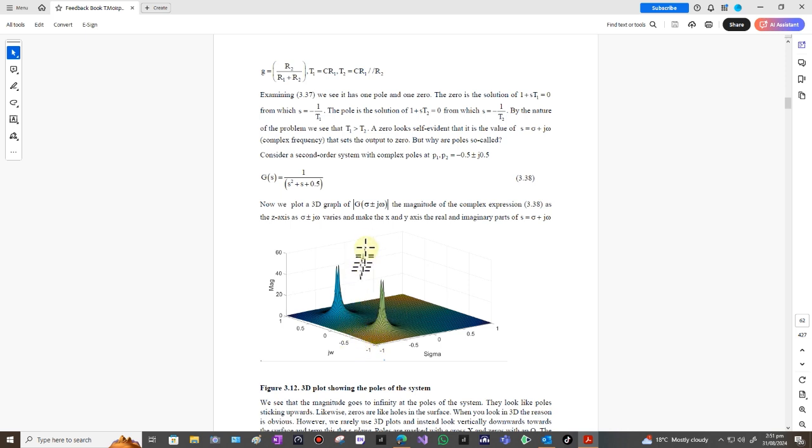So the S-plane comes from this 3D plot, rather. Looking down on there is the S-plane, and as you can imagine, we don't use negative frequencies usually in control systems. I know in signal processing we do, when we do FFTs and so on, but even there we kind of get rid of them normally, eventually. So we're really only interested in a slice through here, and the way it's been drawn here is that the positive frequencies are going in that direction rather than that direction, but never mind.